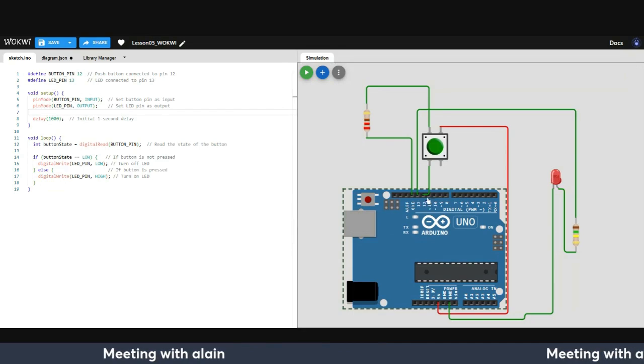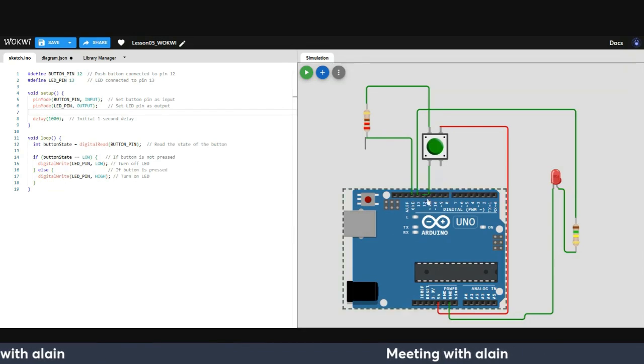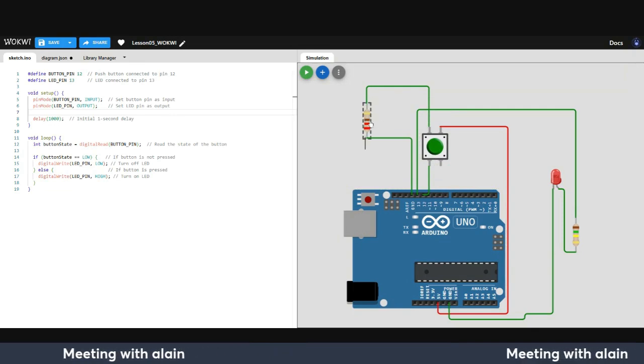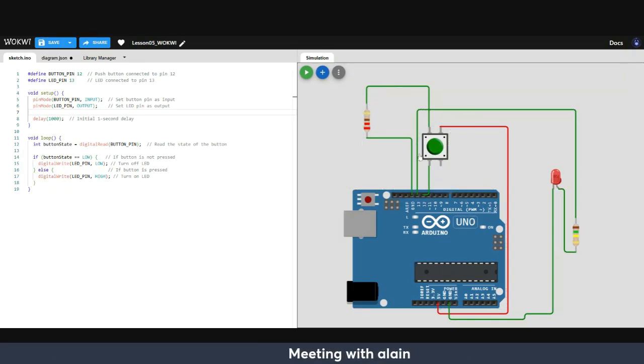We have the push button; its status goes to port 12. We see that the status is directly connected with a little resistor to the ground, to not let the status of port 12 float in the air. We put it to 0 to be sure this is 0.